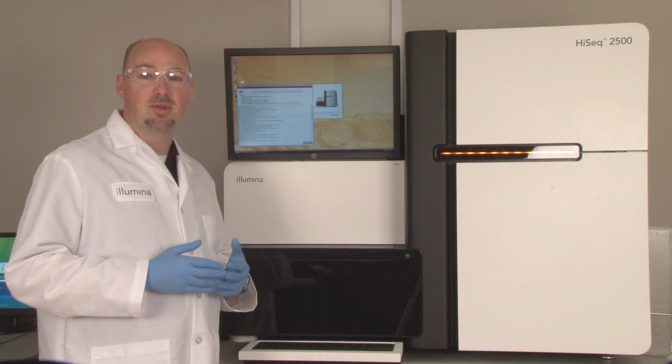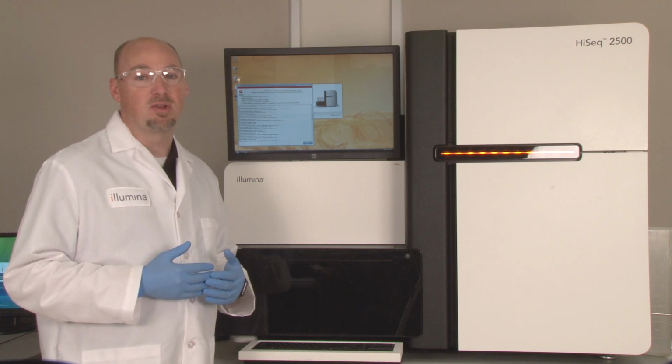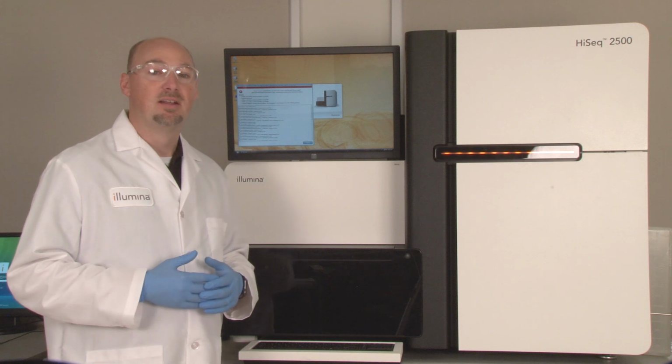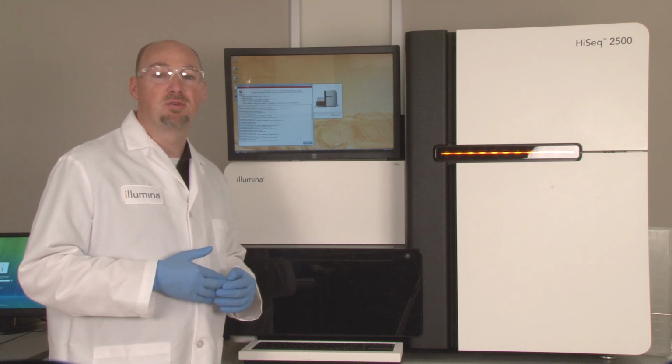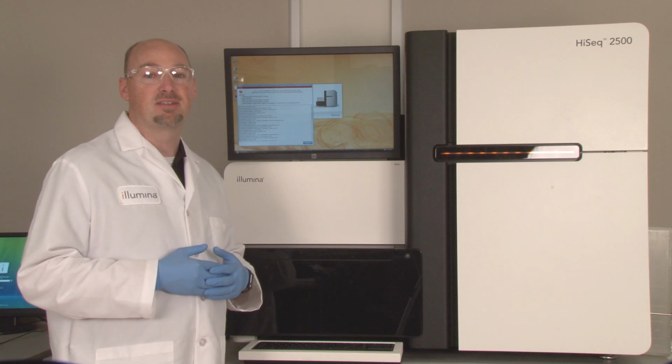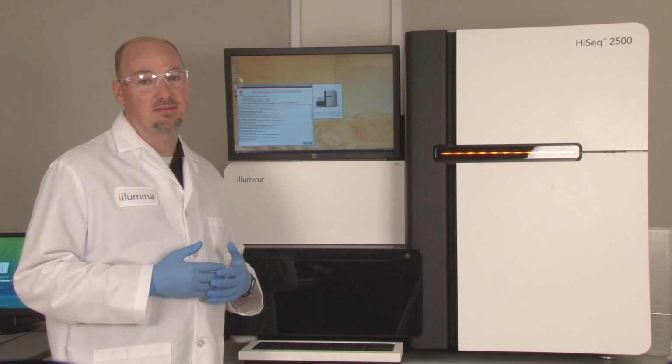To correct this, we can use a program called Port Manager, which can release all existing communication port connections. When your instrument PC is restarted, all communication ports will reestablish in the default configuration, usually resolving any existing communication disruptions. Here's how to use Port Manager.